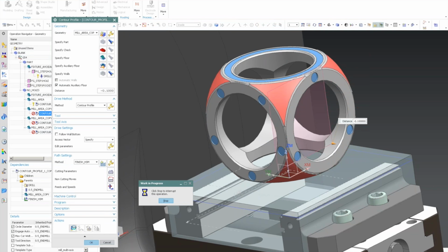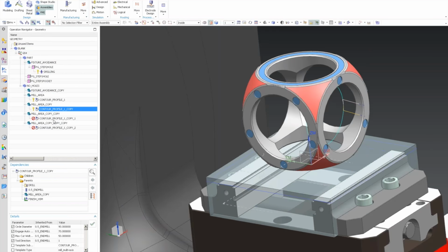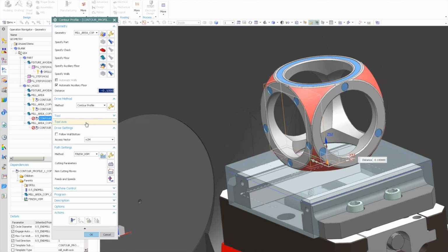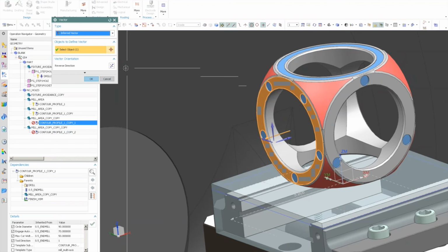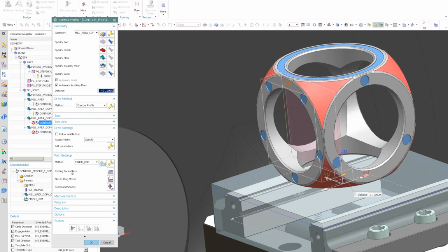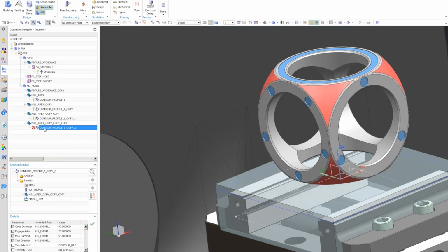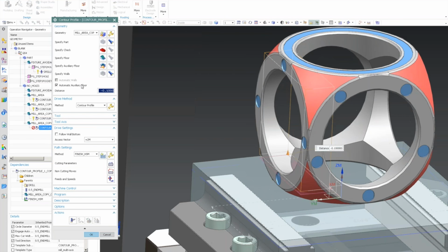And generate, get my second here. So I'm just basically telling it what direction to enter from. We certainly have toolpath types that you can do all of these in one, but like I said, I find this one really easy, and it's a great way to introduce someone to 5-axis.